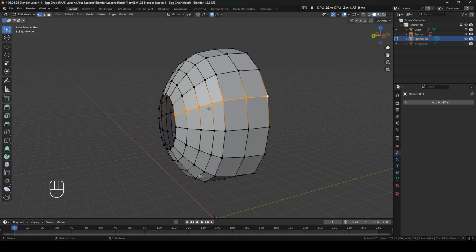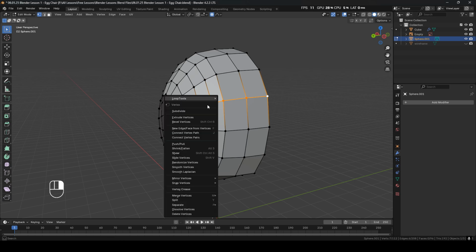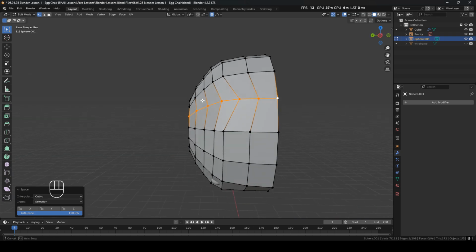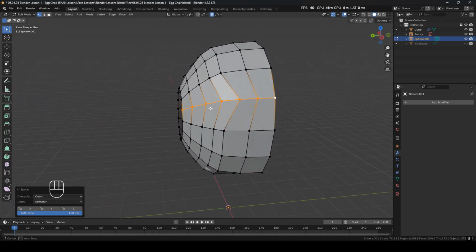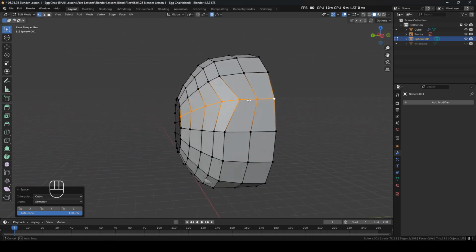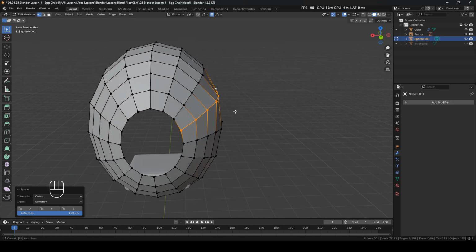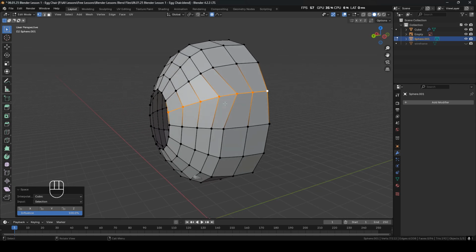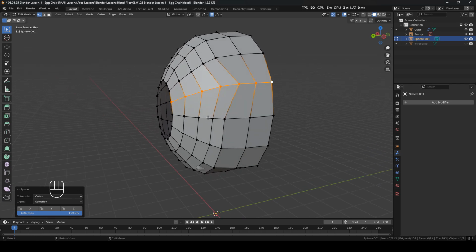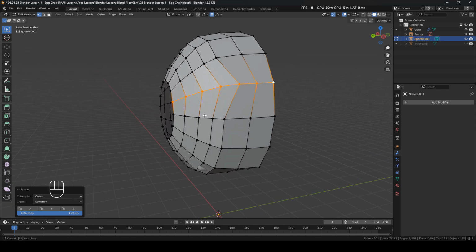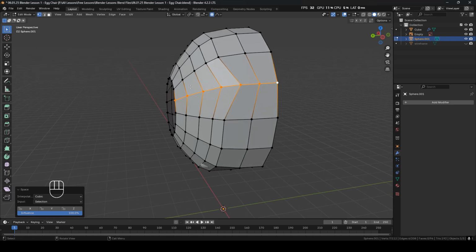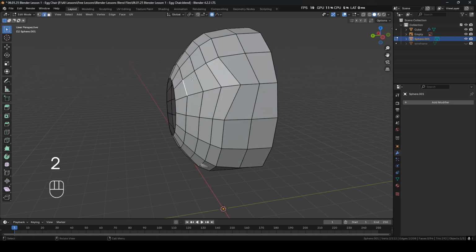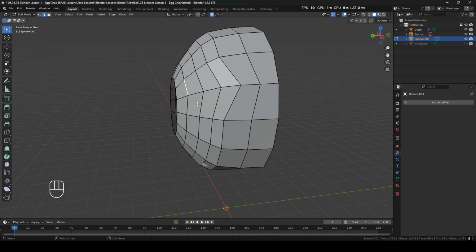Now you can select your vertices. That's number 1 on your selection. Press right click, Loop Tools, and then Space. Okay, don't worry, this will look a little bit jagged like so, but it has done exactly what we need it to do. So now, like earlier, when I was explaining on pressing 0 on your scale, we're going to now scale these edge loops to the Y on 0.